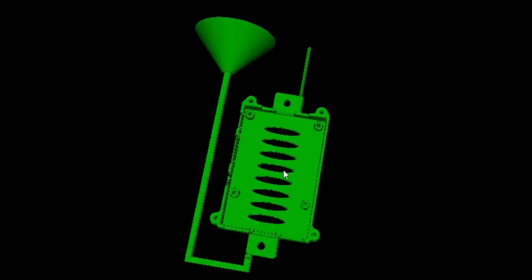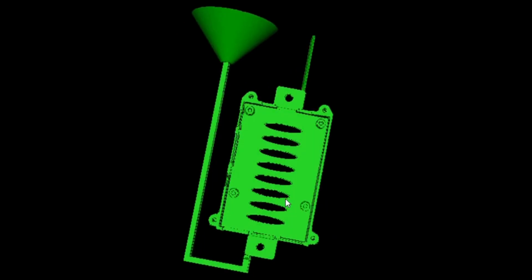So here's an example of a part that benefits from a sprue and riser. You want all these surfaces to look nice and you don't want to see any evidence of the pour. So you add a funnel and a sprue here. This becomes part of the mold, and then when you pour in the resin, it goes down this sprue, it fills the mold in a very controlled way. And then you have a riser over here to let the trapped air escape so that the mold can fill. And then after it cures, you take it out of the mold and you clip it off here, and now you have your part.